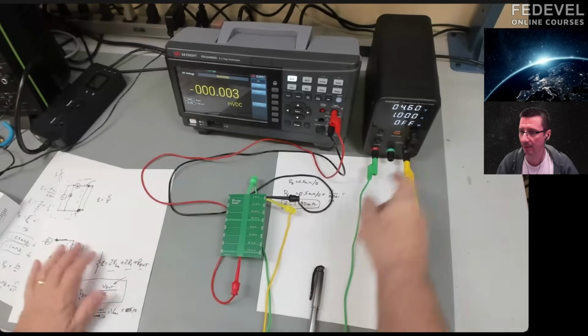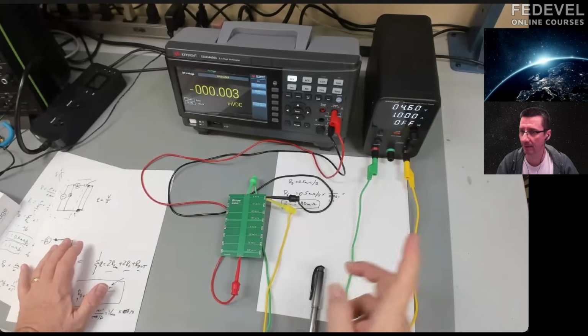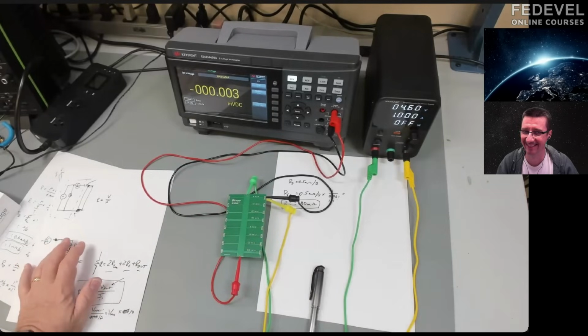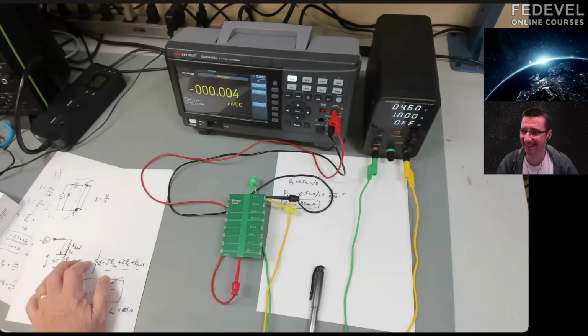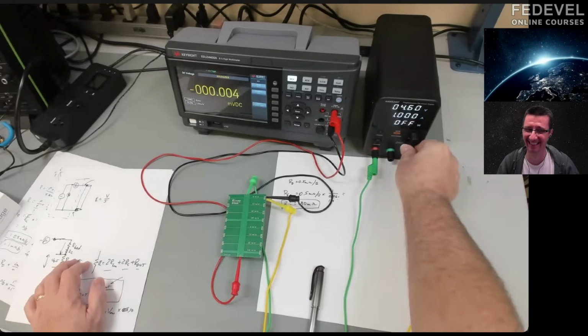And now let's, instead of an amp, because that's 6 mils, that's really narrow, right? That's like the cross-sectional area is thinner than a human hair. So 1 amp, uh-oh, that may blow it up. So let's drop that current down. So let's go to 0.1, like we did before.